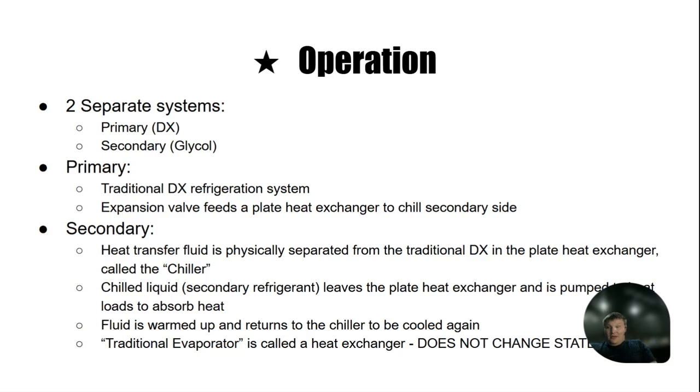Now, again, to reiterate, the secondary fluid, the glycol, is chilled by the rack, pumped into the store where it picks up heat from inside of the store, and is pumped into the heat exchanger where we exchange heat between the rack refrigerant and the glycol.